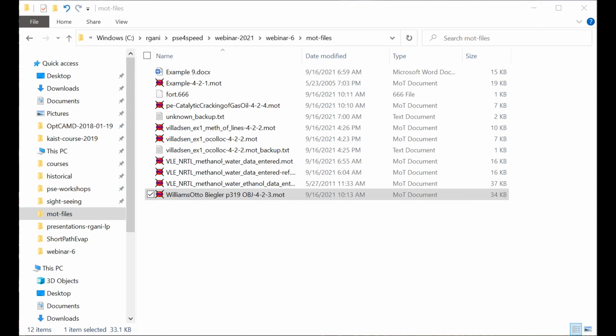Again, we go to the classify variable. Now you can see a lot of red color. The red color is because these are implicit algebraic equations and the variables related to them. The dark blue are the parameters. If we don't want to see the parameters because they are already specified, we can take them off. Then we just see the explicit algebraic equations and the implicit algebraic equations.